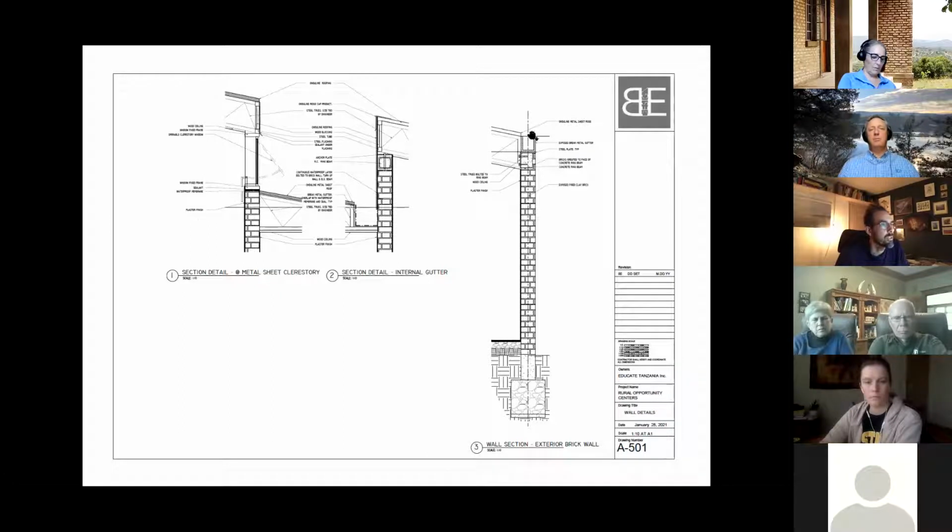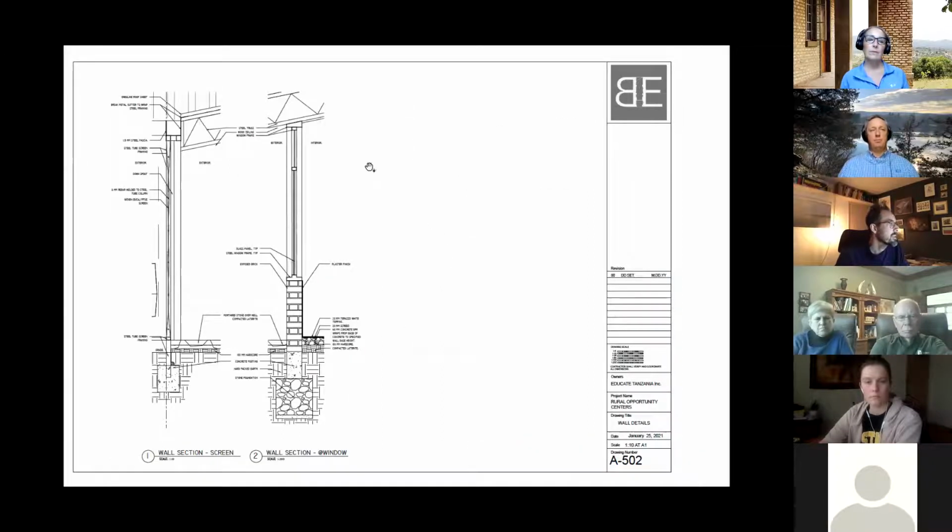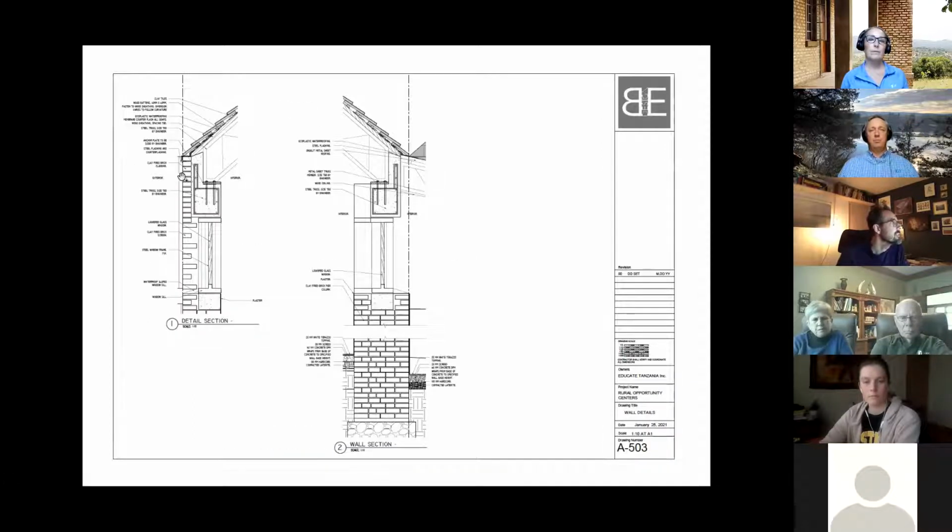And then these are just some of the sheets that are being produced for details. You can see some gutter details, ring beam details, how the truss attaches to the concrete ring beam, brick layouts down to the floor finishes and the foundation, windows to roofing to gutters, waterproofing, just things that we're starting to work on and get into more detail to test the building and see how buildable it is and what materials and details go into it.